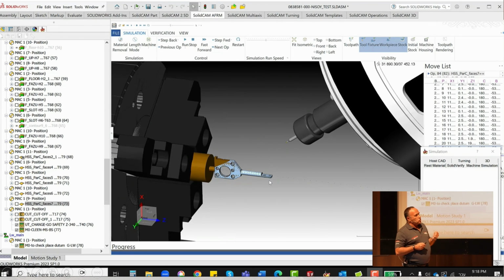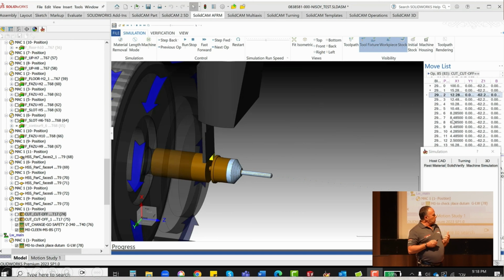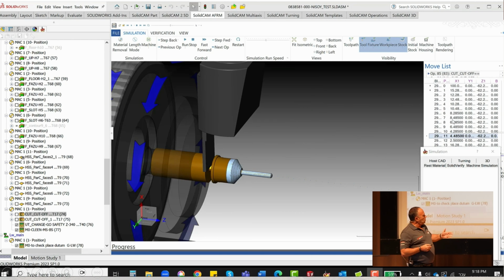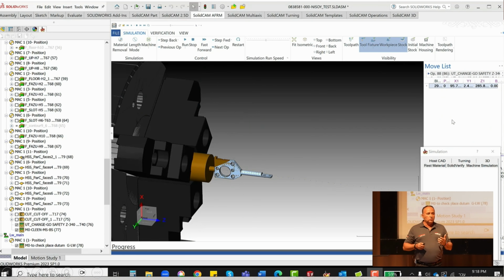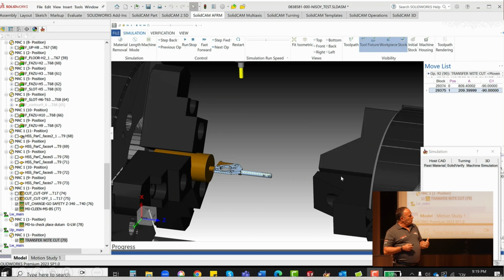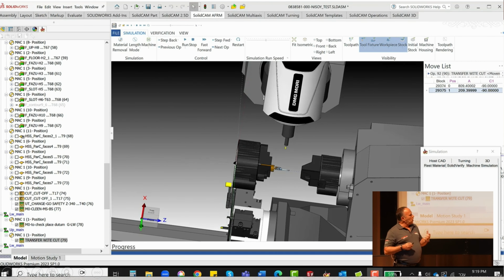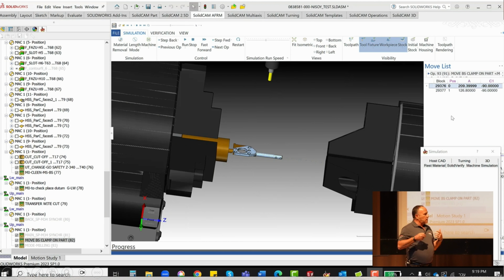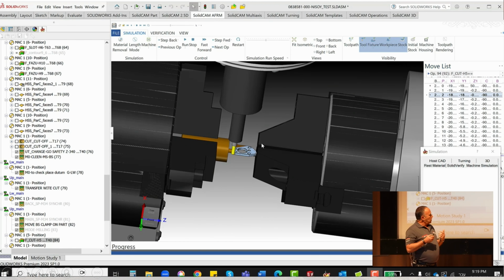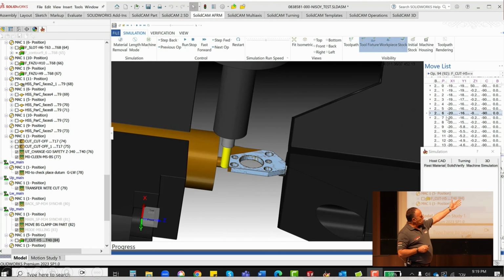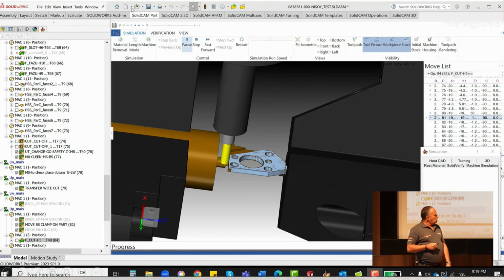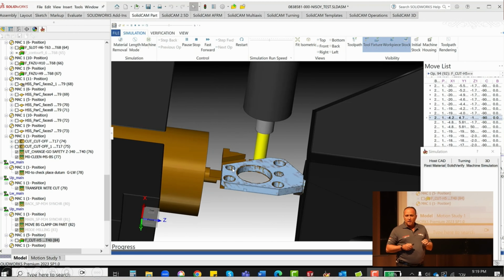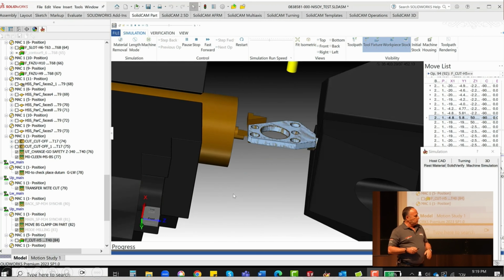And now, what is the challenge now? The challenge now is to disconnect the part, to disconnect the part with the right dimension, of course. So we start with some grooving, turning with the groove tool. And now, how do we do it? By our MCO, we will call the back spindle. We will hold the part now from both sides, so we will have a very stable clamping. And now, with the finish profile tool, we disconnect the part and also get the right size. So this is not complicated, but it's a very smart way to program a part in mill turn.